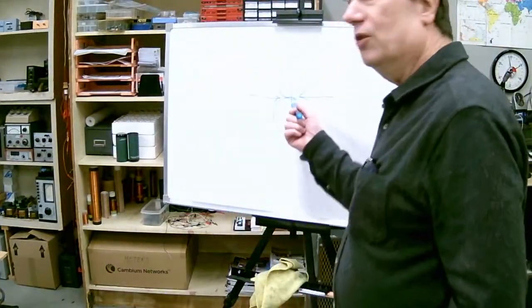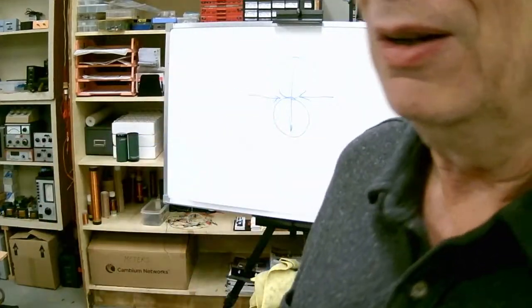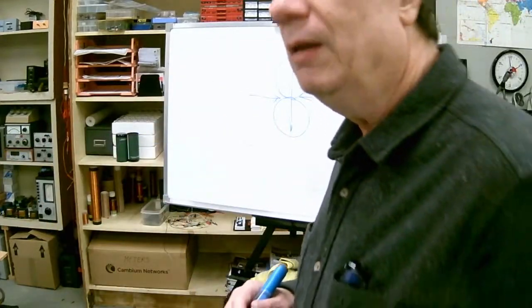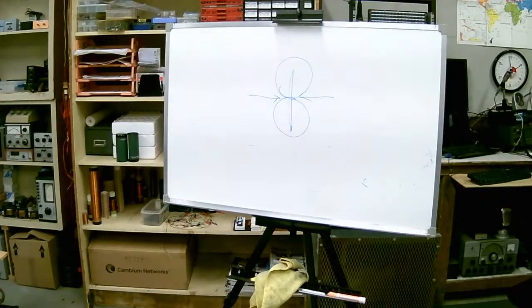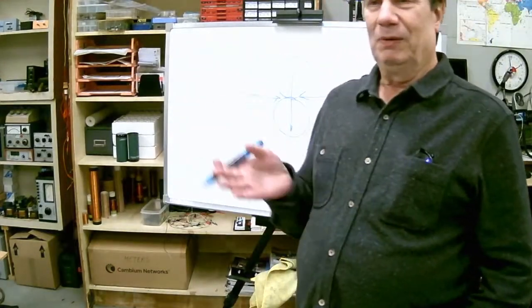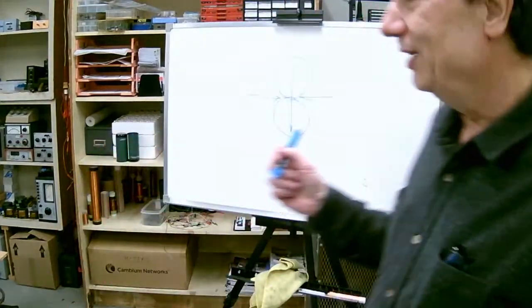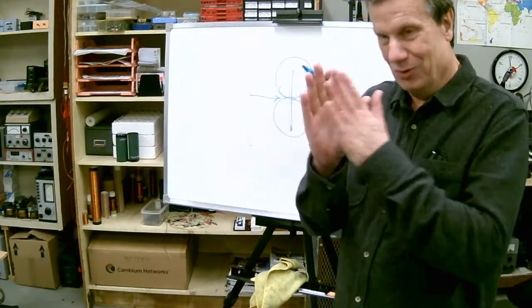So this is what's used in all your automatic direction finding on aircraft. You use a beacon, and where the signal goes away is the direction. With high gain antennas, you'll find out that it's always easier to get a very sharp null than it is to get a very narrow beam.